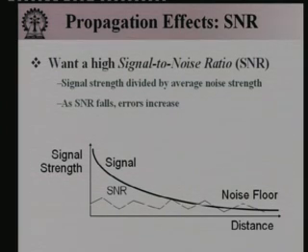So, in this figure you can see that as the signal becomes weaker and weaker and touches the noise floor, maybe goes below it, that means the noise has become more than the signal, then no meaningful communication can be carried out. So, in general we want a strong signal to noise ratio. One thing we might do quite often is that suppose we have to send a signal to a very long distance, and the signal will naturally get weak.